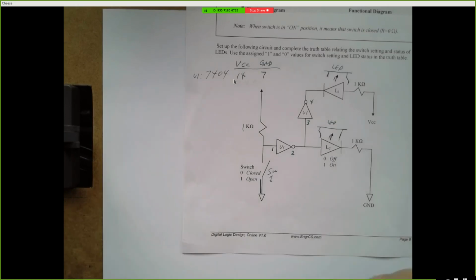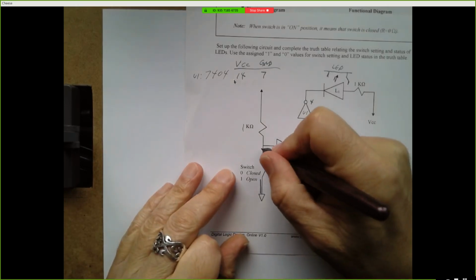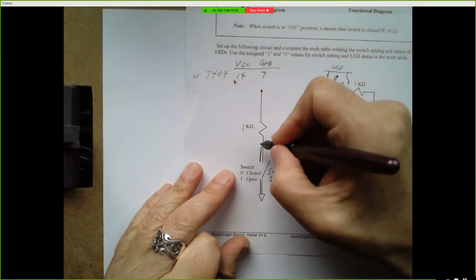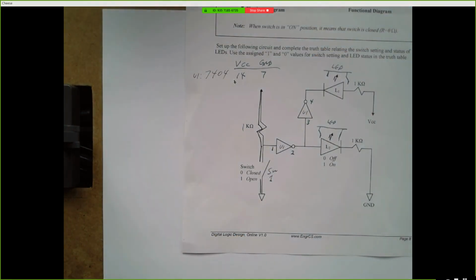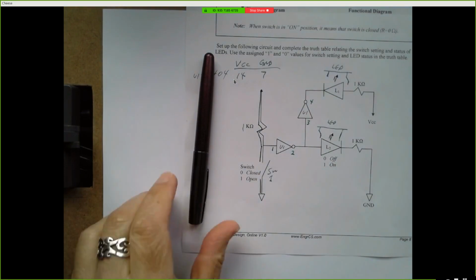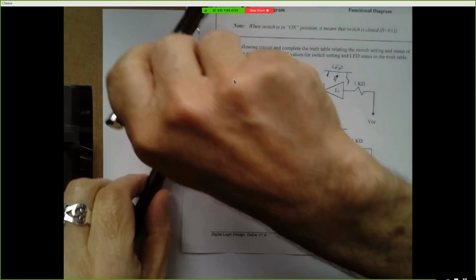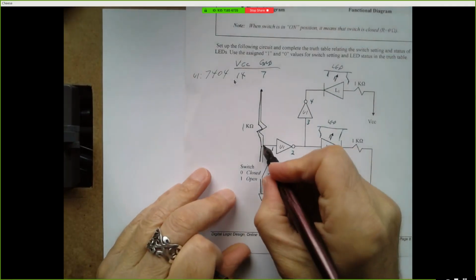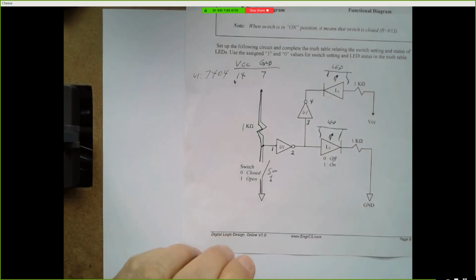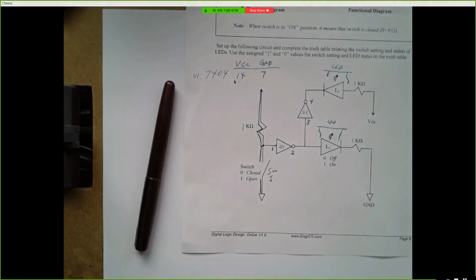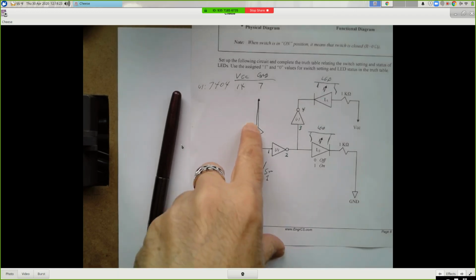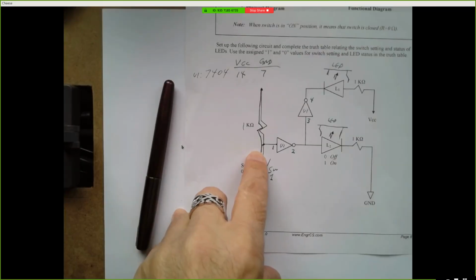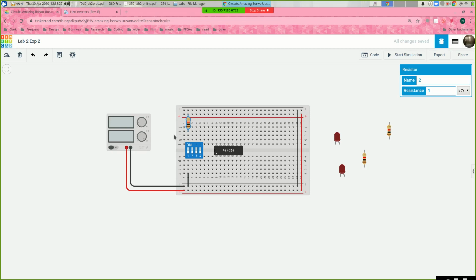Okay, so now I've built this. I'll put that wire up to the 1K, and I put that up to 5 volts. Okay, so this part is done. All right, from here I want to connect to pin 1 on my chip. So let's just run a wire. This point right here is where the resistor meets the switch, right? That's where the resistor meets the switch.